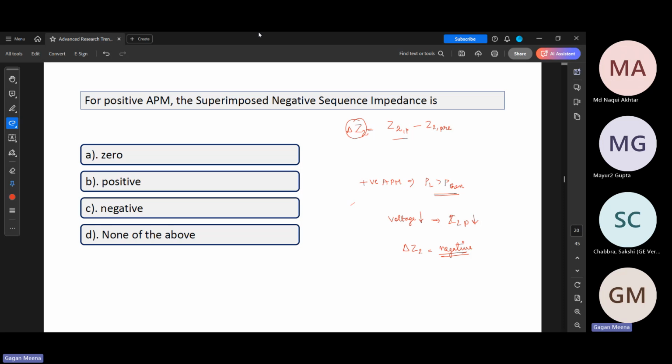Although you are saying that even in distribution systems these inverters are designed like that, right? Yeah, correct. Even in the inverters which have fast frequency response, those inverters also work, as far as I know, in PQ control mode. P is for if the frequency drops, say to 49.4, then they are supposed to inject more active power.